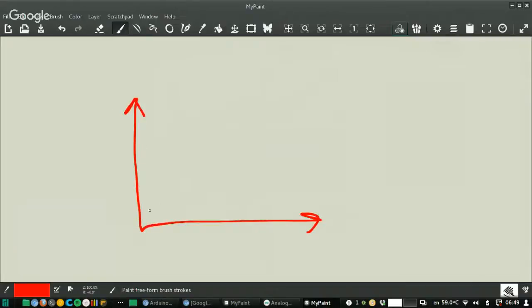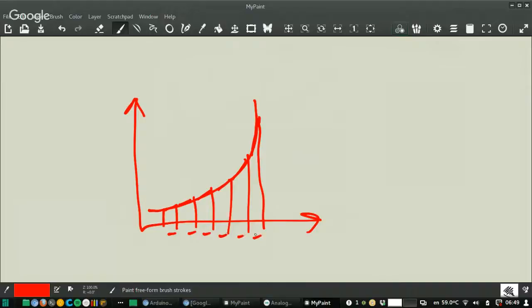And finally, if the sensor is like this, there's not any sense to read it in analog, or you have to build your own function that approximates this in linear stages for every given range. So these are more complex. We are not doing this now, but take into account that if you are doing something that is not linear, you cannot do what we are doing now. You have to divide the values of the sensor in small chunks. Okay.